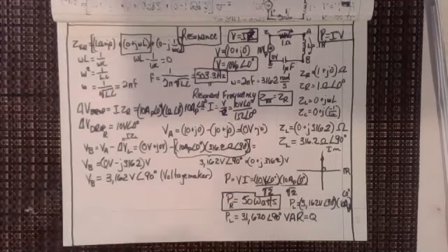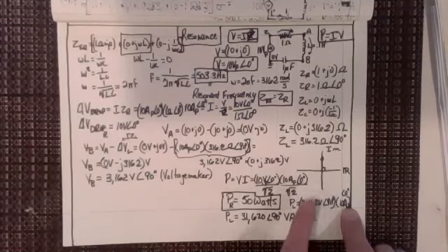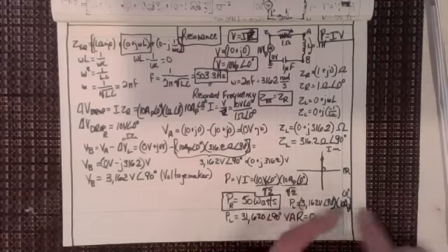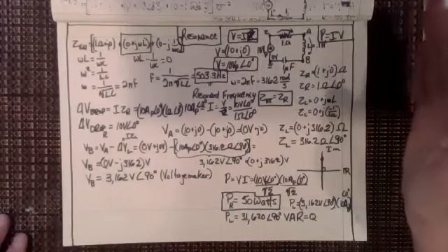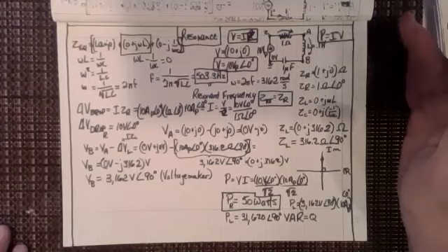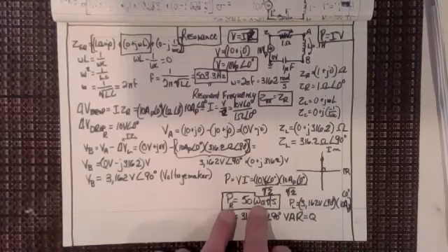I've shown you that before, that the phases of the current and the voltage are different here, right? So they give it up and then they give it back, and then they take it and then they give it back, and they take it and they give it back. So there's no real power flow except for that 1/4 cycle of the wavelength. So this isn't stuff that's really lost, but this is stuff that's really lost.